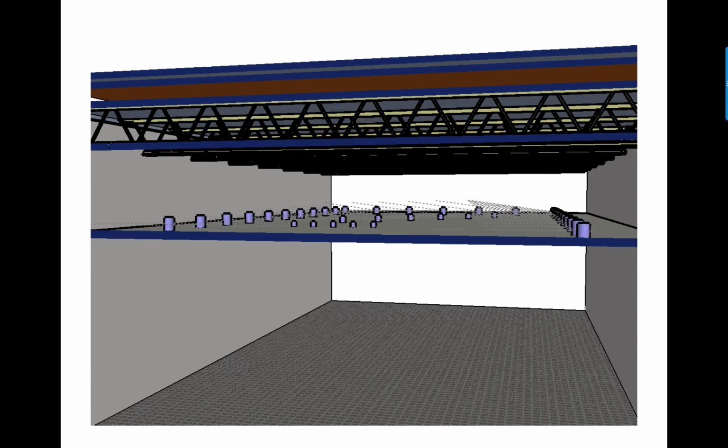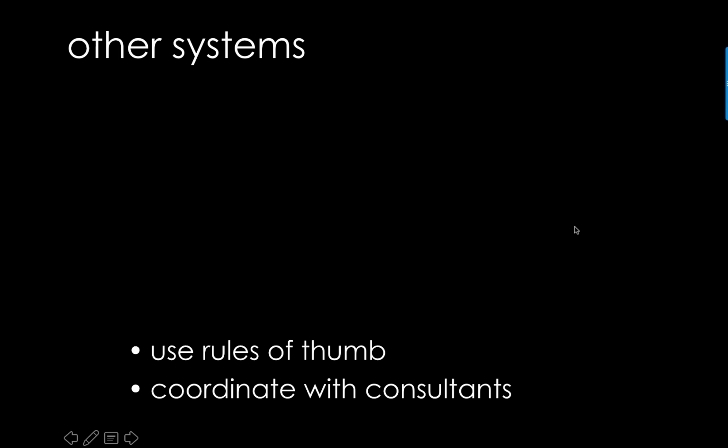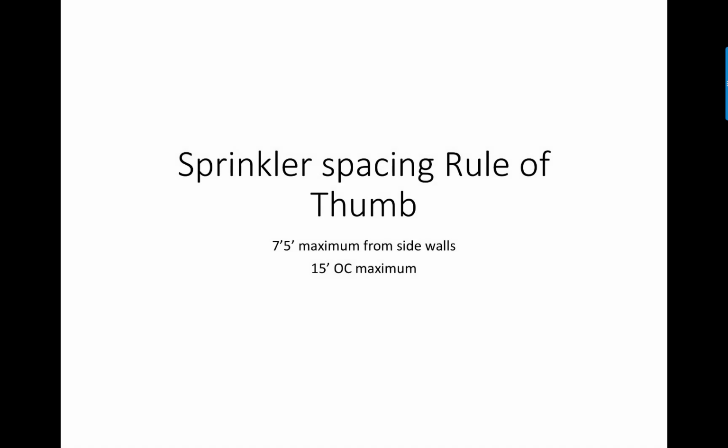Not the ductwork, but the plumbing, and then the sprinklers, and then you've also got the recessed lighting. Like I mentioned, those have some dimension. So getting all those things in there is quite a challenge. There are a few other things that we stick up in our ceilings that typically you use rules of thumb to get you through the design phase, and then during design development in a larger project, you would usually have some consultants that you'd want to call in.